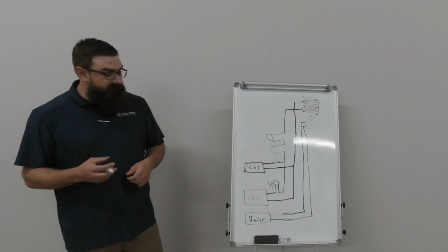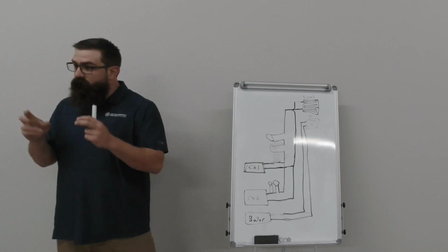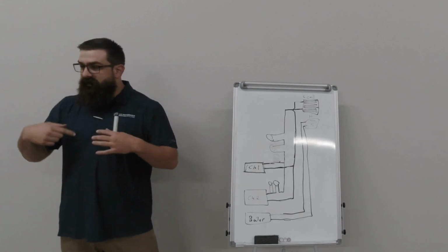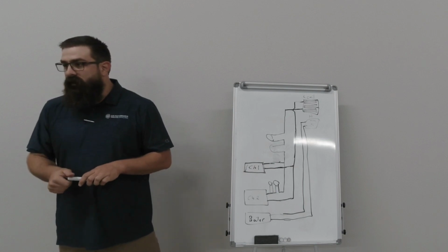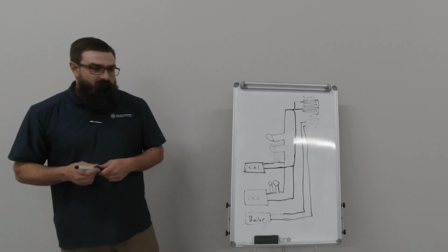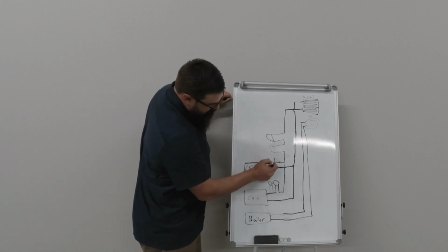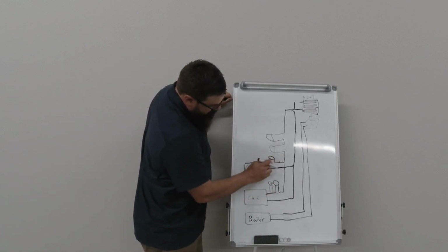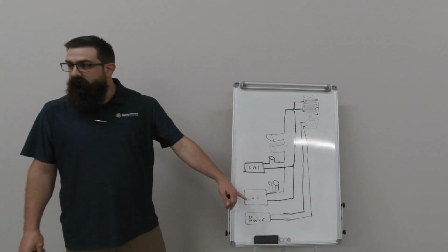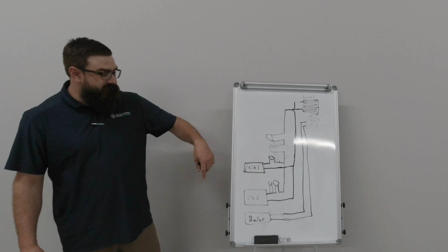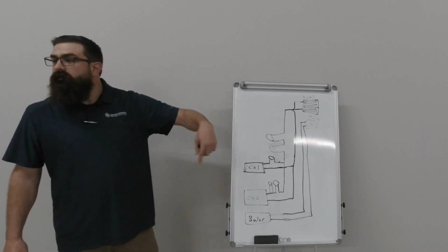Now there's something we were going to touch on a second, which is called primary secondary. So primary secondary is you have a pump on both sides. You have something that does the primary loop, which is your building, and then the secondary loop, which is like inside your central plant. So that's getting even more into things. So that would be basically a combination of these. So you would have a pump on each chiller that pushes through the chiller itself to a common header, and then you have pumps on the building.